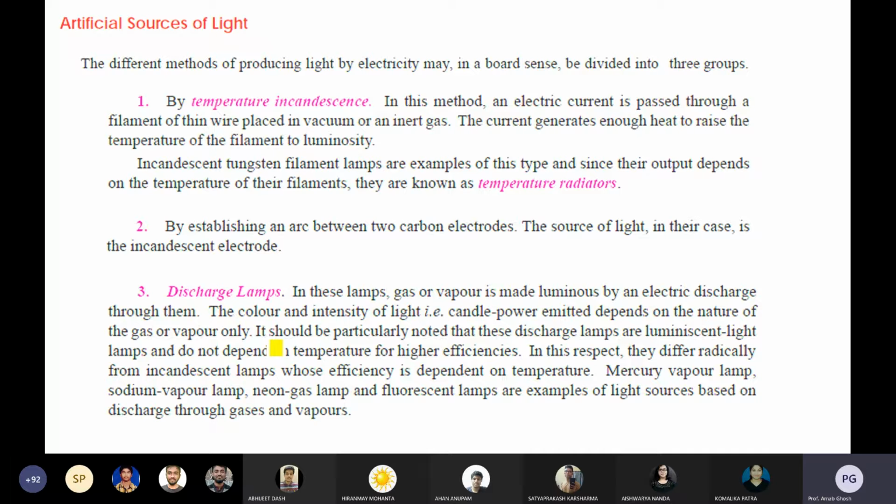After some time, due to that high potential difference, that medium can be broken down, and there will be chances for the flow of electrons. After the flowing of the electrons, that may be responsible for the flow of current in the reverse direction. That is the concept of the fluorescent lamp. But as I am telling, there is the inductor, and you can understand how much losses there will be. And as it will be bulky in nature, a lot of coiling will be there.